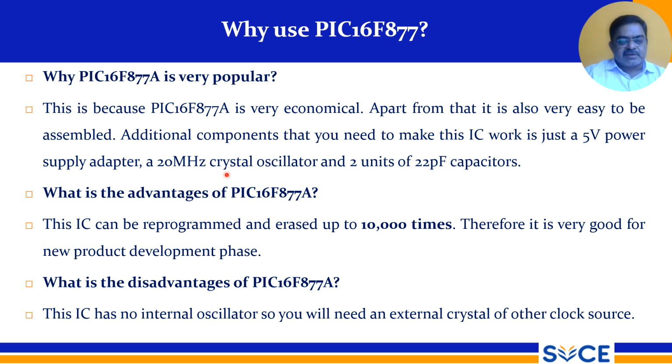So if you have a 5 volts power supply adapter, you can incorporate this in your embedded system very easily. A 20 megahertz crystal oscillator and 2 capacitors, that is 22 picofarads capacitors, are required. So very easily you can embed this.